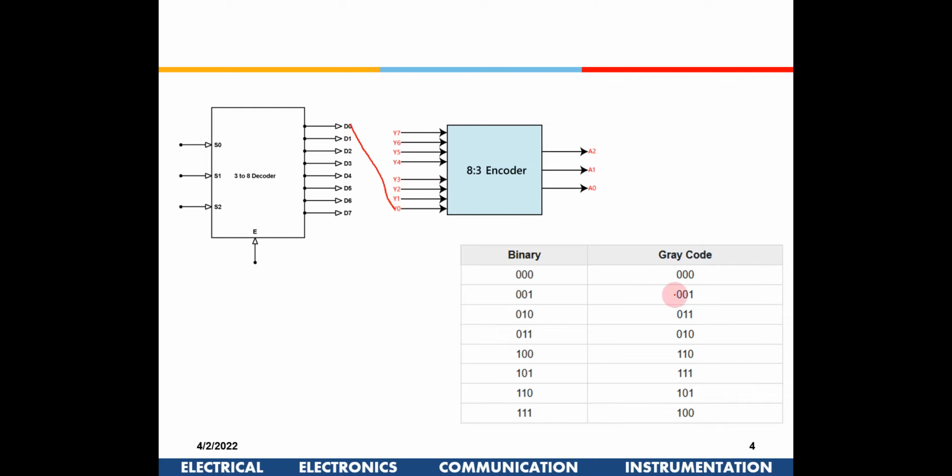And for 1 it is going to be 1. So I am going to give the same 00. If I give 000, this will get activated, and it is connected to 00 here. So 000 will be available out here, right? If I put 001, this will be activated. So I get it to Y1 out here, right? So again 1 will be activated.